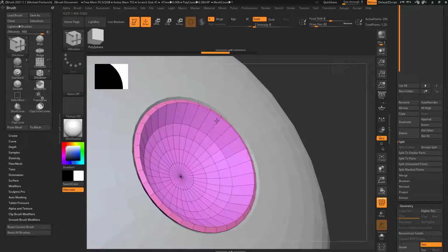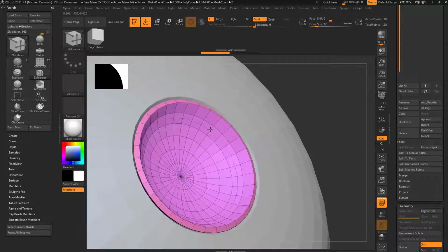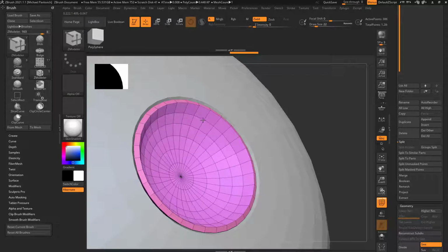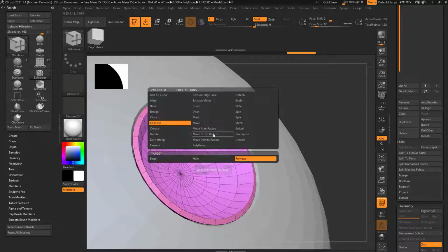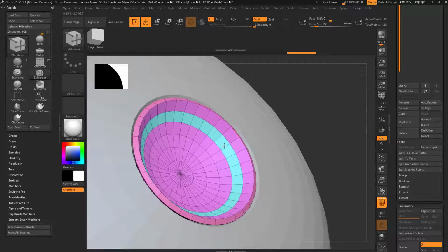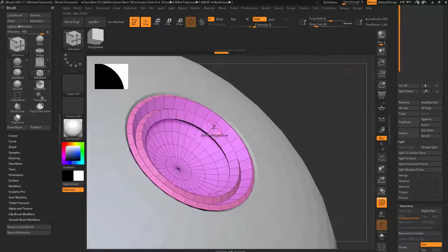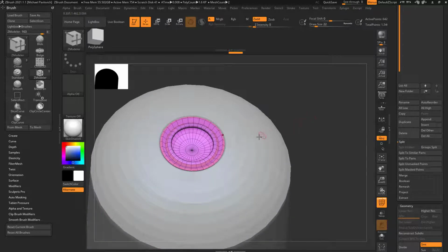Now let's say you wanted to collapse these to a center point along here. What you can do is insert multiple edge loops, and that'll allow you to put an edge ring right in the middle here, and then you can collapse poly loop and collapse that one up and this one down, and that'll collapse to the middle. And just like we did before, you can bevel, hover over a face and say Q mesh, insert multiple edge loops, pull and round it off, and get all sorts of modeling happening for whatever you need to do.